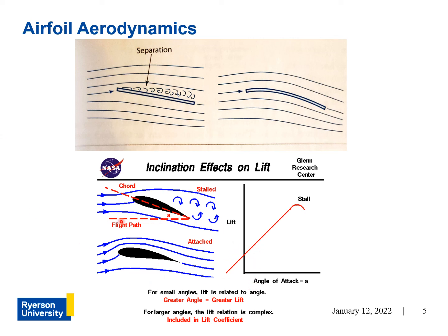Now, different shapes of airfoils have their own characteristic lift curve plots. So depending on their shape, this region where it's attached, it's still going to be linear, but they're going to be of a different slope. Later I'll show you a bunch of variations on the lift curve slope.